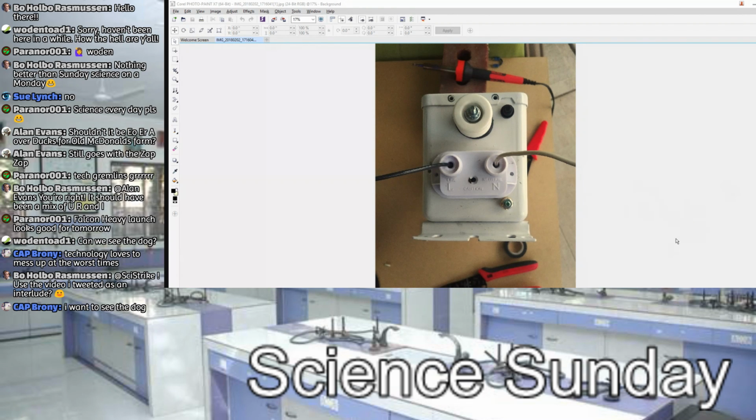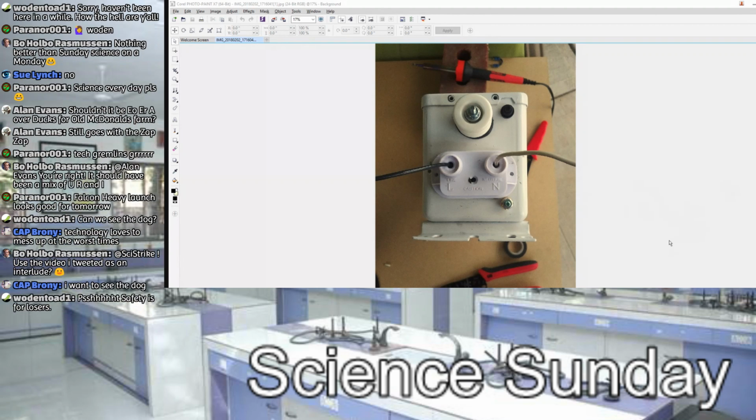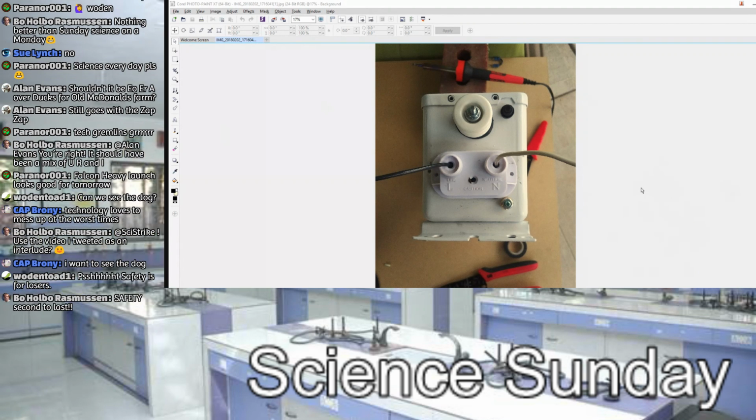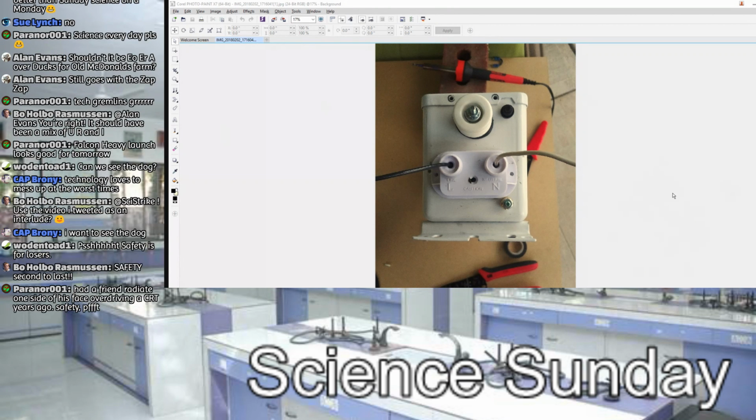So neon sign transformers, if you're not sure, they're center tap. As opposed to a microwave oven transformer that's a coil next to a coil, this is a coil in between two other coils. So you basically have one line coming out at 6,000 volts and another line coming out at 6,000 volts. It makes it a lot easier for insulating and making things. Instead of having to actually insulate for 15,000 volts, you only have to insulate for 7,500 volts. But all that ground fault interrupt circuit has been completely removed, and modified a little bit there.